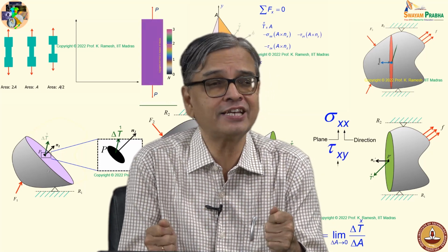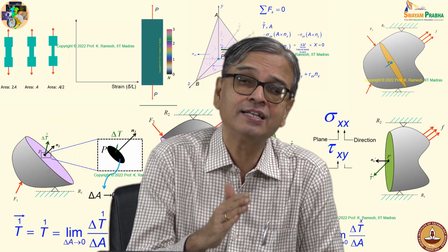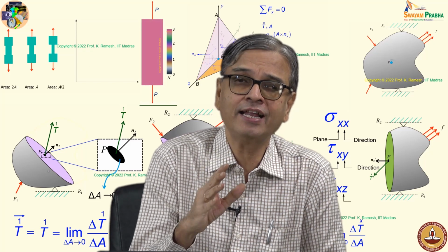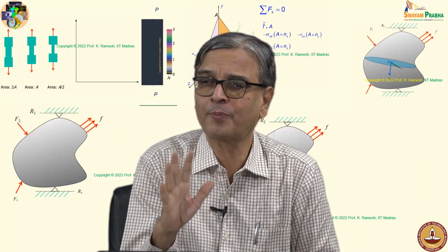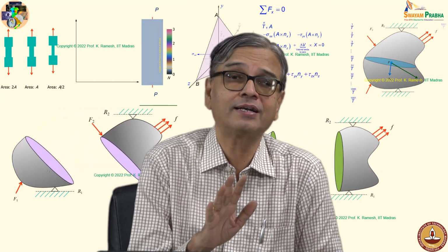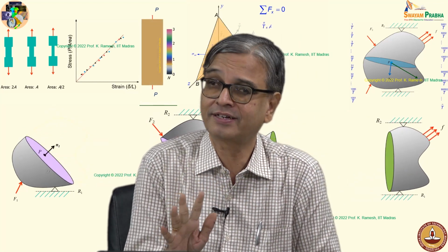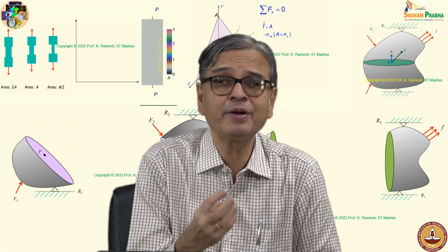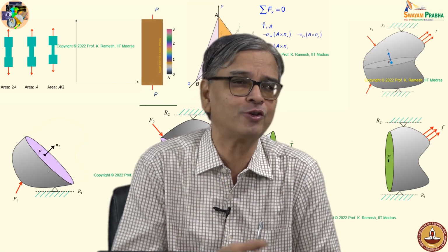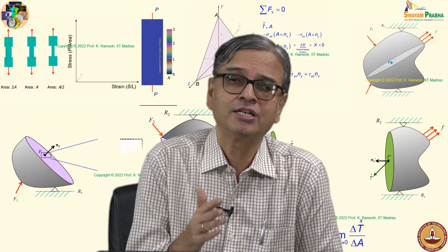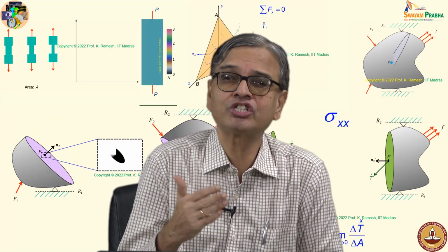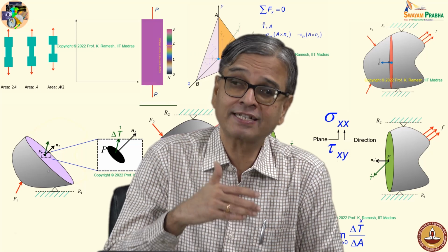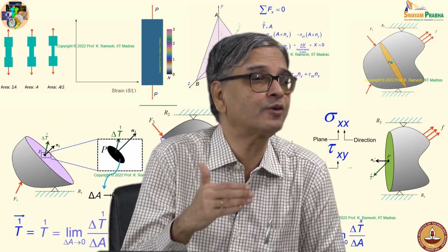Even in a simple axial tension, if I look at different planes, some of the planes can have both normal and shear stress, and we had done one type of graphical plotting. Polar plot is what we have looked at. The polar plot, the representation was beautiful. Nature really loves beautiful patterns, but to cull out the information that we want, it is a little difficult for you to do that. And what we noticed was, you can identify two planes in which the normal stress alone can exist. But when I have maximum shear, you always have some amount of normal stress.